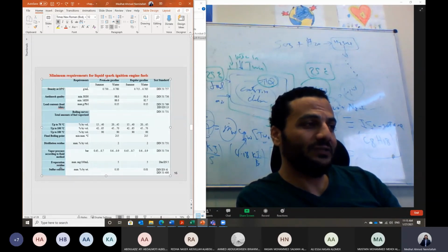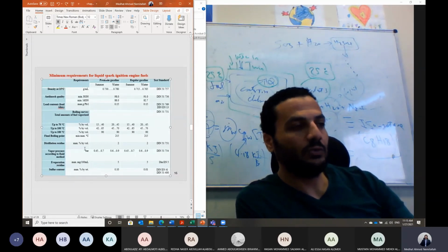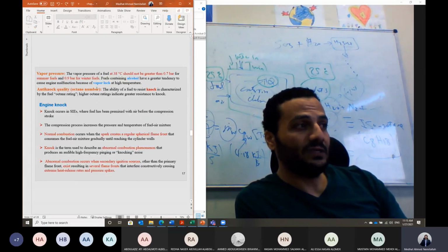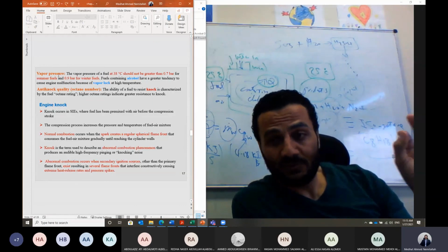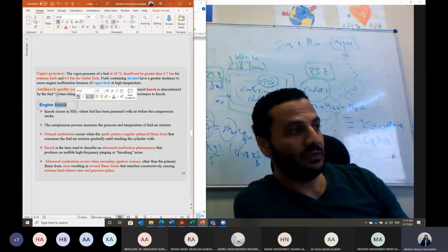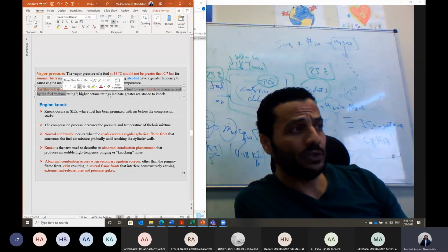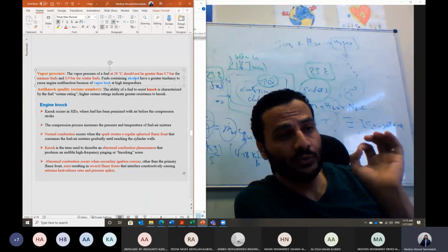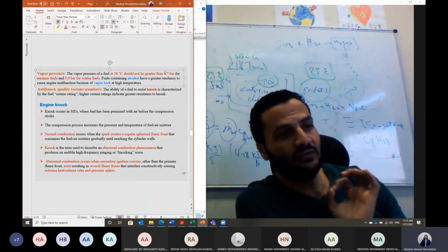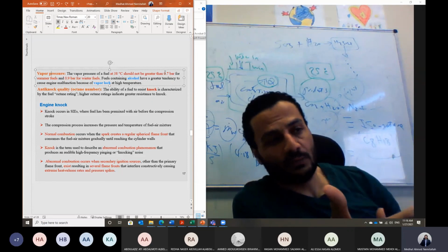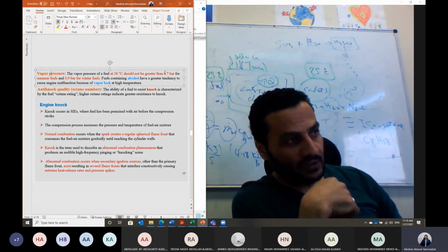The sulfur content, guys, and the evaporative component, all of this should be at the minimum level in the fuel in this case. Vapor pressure, guys, this is the last point here. I will stop here. Inshallah, next time I will be talking about the octane number and the engine knock. Vapor pressure of the fuel should not drop below a value of 0.7 bar, so that the fuel does not vaporize and cause vapor lock at the engine cold start.